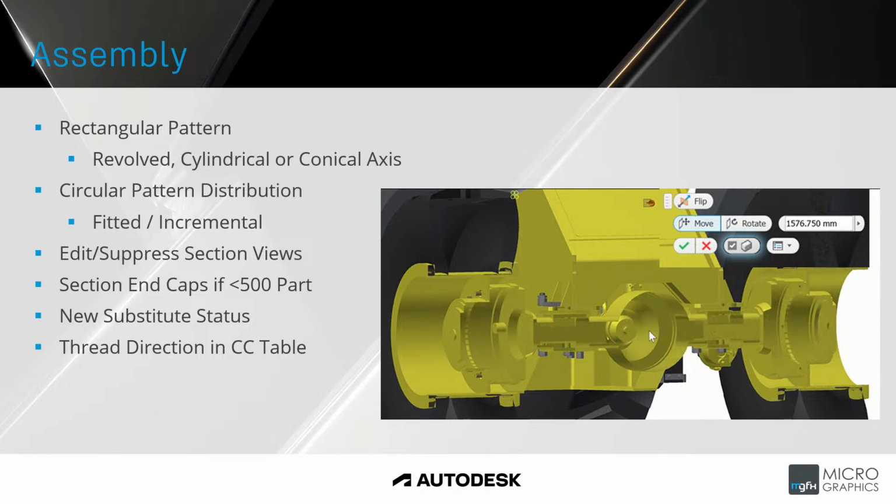You can see in the animation here on the right, with the end cap displayed, you get that material texture, and that takes time on larger assemblies to actually update when you edit the section. So if you have an assembly that's larger than 500 parts, that end cap will not display, but you do have an option in the heads up menu to enable that end cap view. We can actually see it here. If I just put my pointer there, we can see the little block with the checkbox next to it to display the end cap.